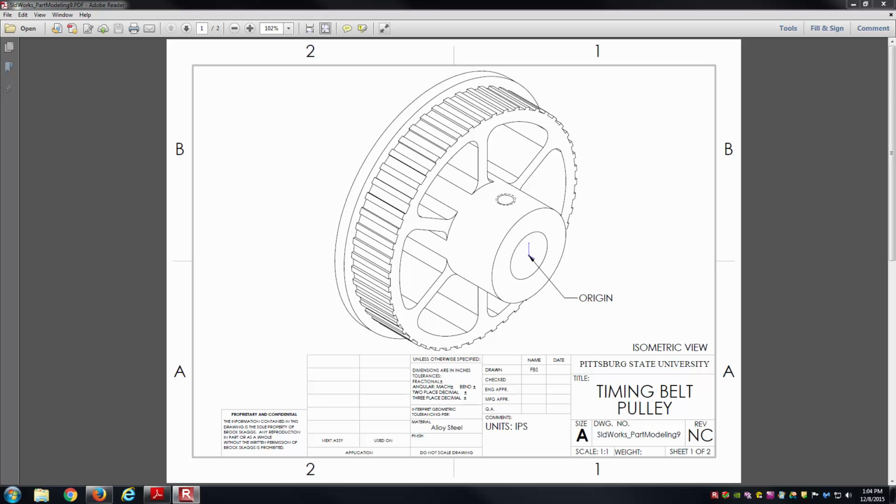One of the things that we'll be illustrating are some of the features that SolidWorks has to help with those types of geometries. Namely, we can use things like the Revolve Boss/Base command, circular pattern, and so forth. Those two probably being the two big ones. You can see a circular pattern of the cut slots in here to create that spoke pattern, and they also have these small ridges that wrap around. You can see the unit system is IPS.